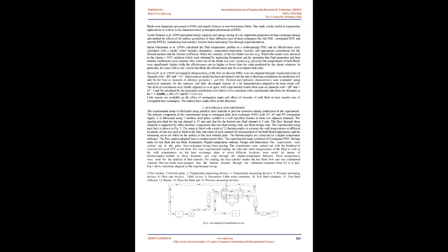This type of configuration approaches the ideal case of pure countercurrent flow conditions, and therefore a simplified mathematical model can be used for parameter estimation. However, it was known that the results of parameter estimation depend on the selected exchanger configuration because the effects of flow maldistribution inside its channels were incorporated into the heat transfer coefficients.